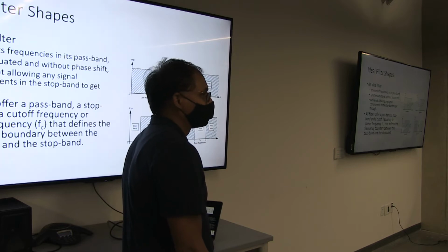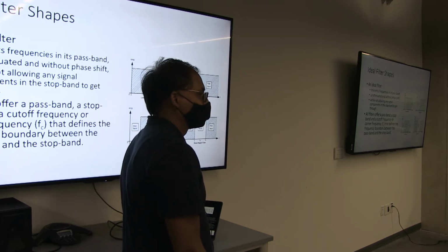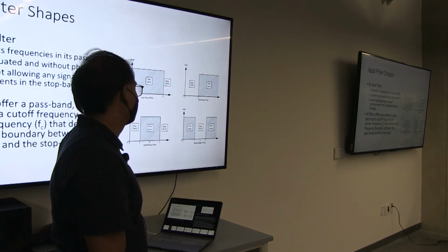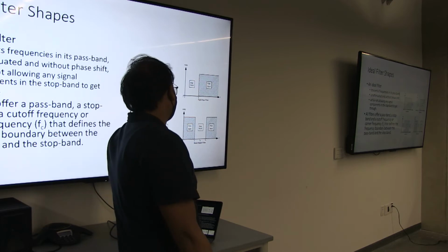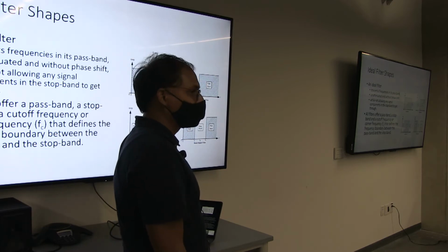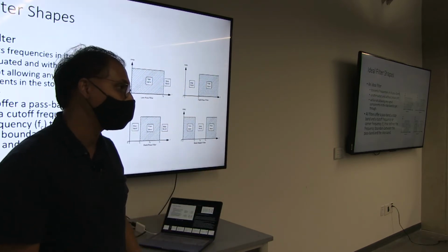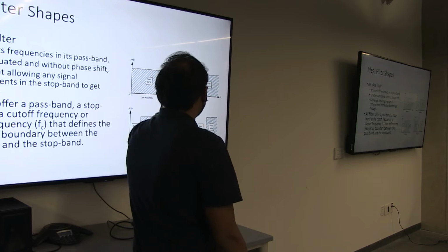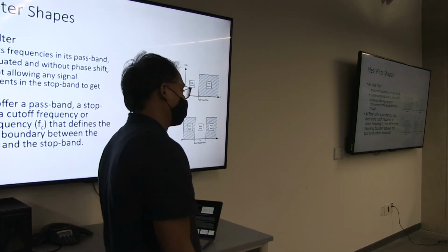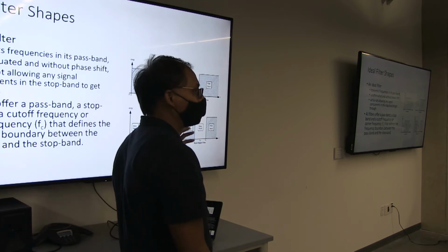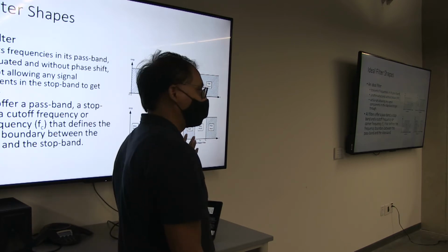Right. fall down. That means here we have infinite poles. Each pole corresponds to 20 dB per decade roll off. So this is very high compared to 20 dB roll off. So we would need a very high number of poles, which is not very efficient.